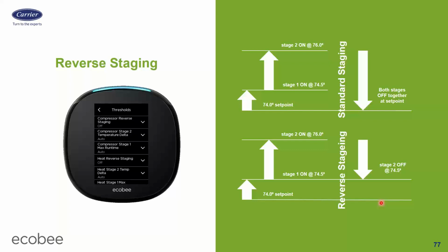So that's how reverse staging works. For heating, it would work the same way. It just would be opposite. When we got below the heating set point is when things start turning on, but it would work very similar to this. Oops, one more arrow I forgot.